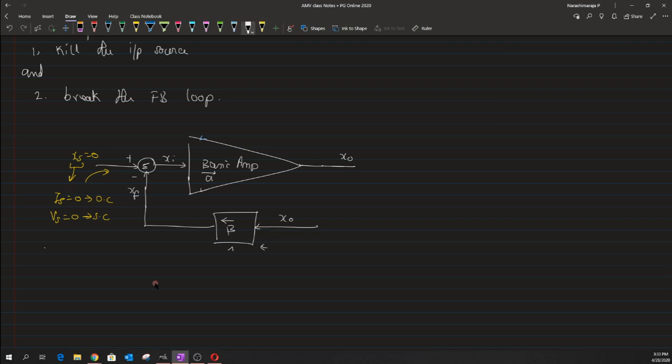Yeah. So, it is something like breaking this particular network connection that I have towards the input of this beta network, and then later to this feedback network input, we will try to apply an input signal which is known as xt, and xt is nothing but the test signal, and in turn, where this particular feedback is being broken out, the signal output is taken as xr. So, basically the xr or x naught is same, and it generally works like this.